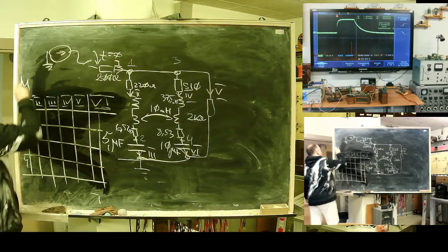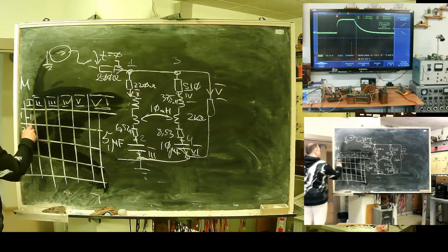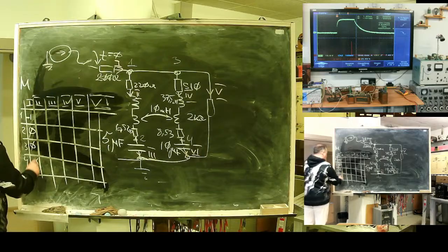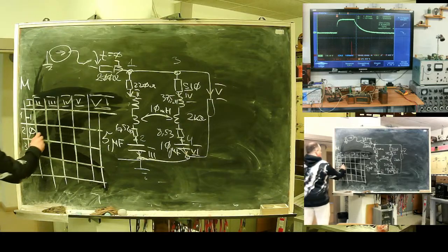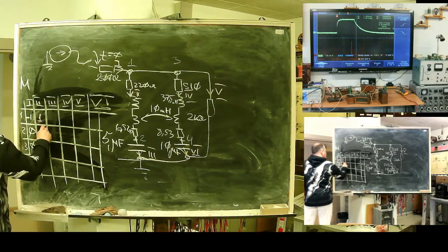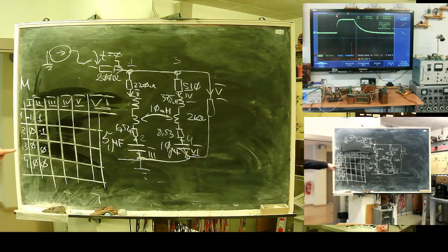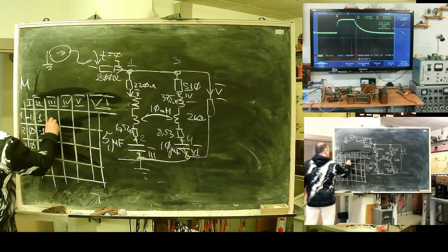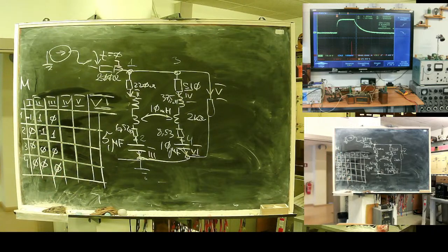First, the matrix of incidence, or M matrix. Branch 1 inflows into node 1 and has no more connection. Branch 2 from 1 to 2. Branch 3, 2 to base. There is no role for the base node, for the grounding point, it's not necessary.